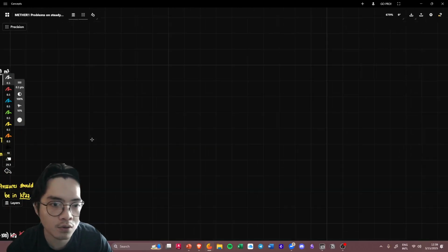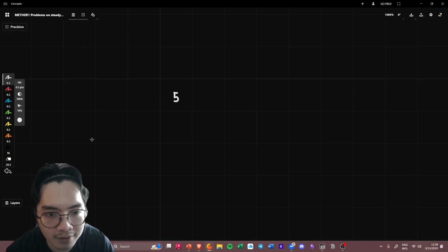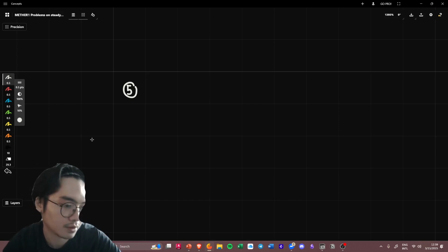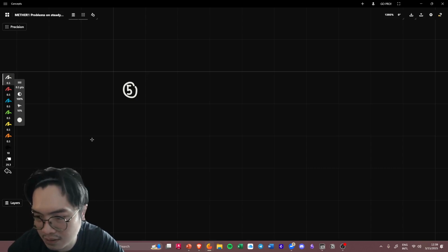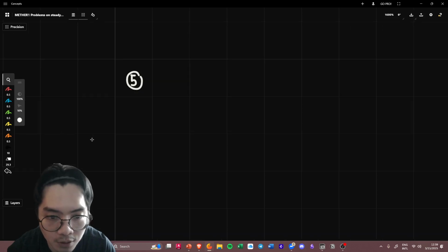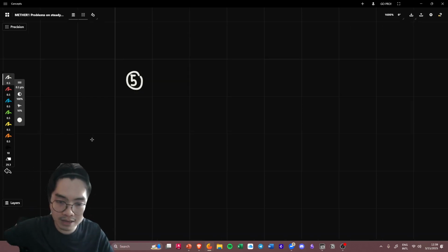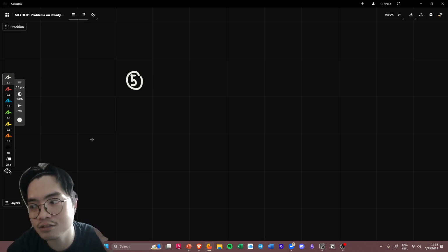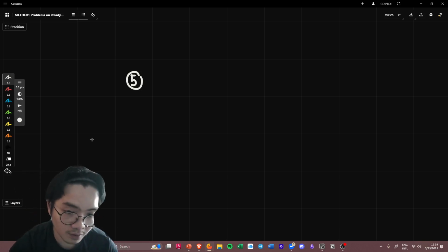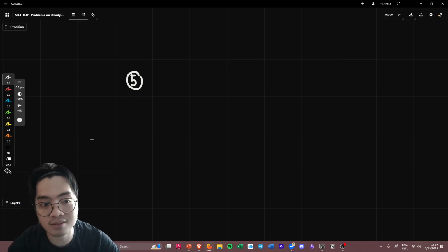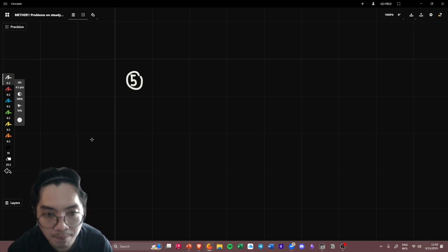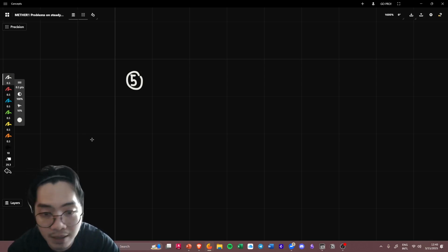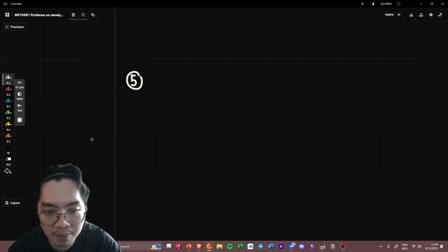So for number 5, we will have a turbine. The thing with turbines is that they are the opposite of a compressor, right? If a compressor compresses something, a turbine's goal is to get energy. But how does it get energy from a fluid? It expands the fluid. Because you're getting energy from the fluid, the fluid cannot maintain that high pressure, so it expands.